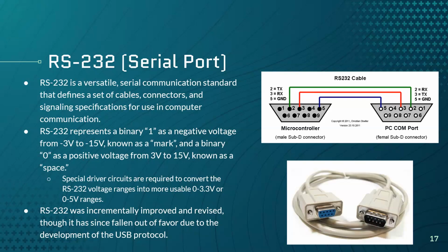Another thing, how many of you know VGA, like the thing the projectors use? This looks similar to VGA. It's not VGA. Don't try to plug them in together. They look very similar. The way I always tell it, RS-232 has 2 rows, VGA has 3 rows. They look really similar, shockingly similar to each other.